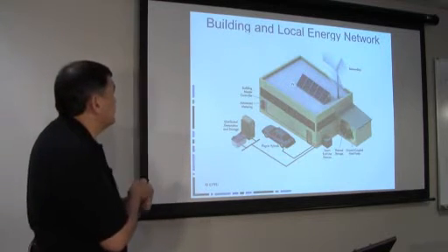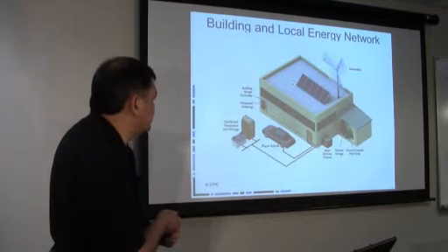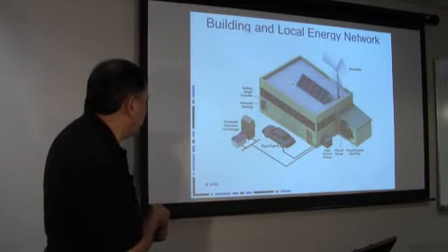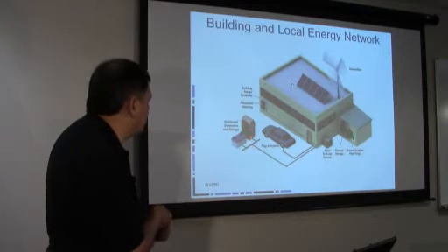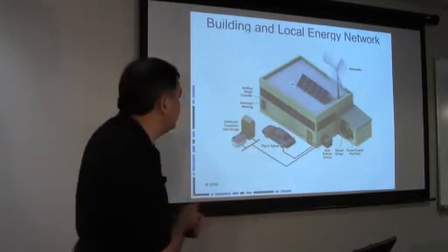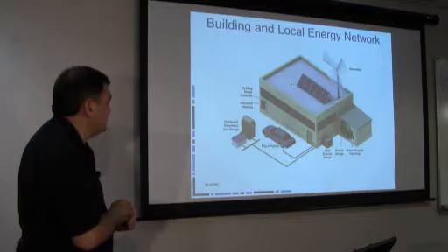We will have building local energy networks. A building may have renewables, wind, solar, thermal storage, heat pumps, as well as plug-in hybrids and distributed generation. We have small microturbines, a turbine that is capable of serving the energy for an office building of, say, 300-400 people, along with distributed storage. And that will have a master controller where, based upon the real-time price that's coming in, and not only the real-time price but the forecast, they will manage all those devices to both reduce their consumption at high prices and even feed back when the price is higher.